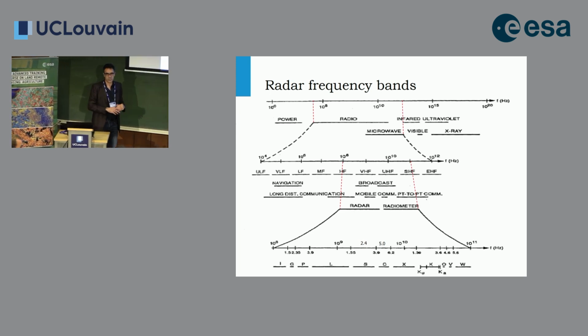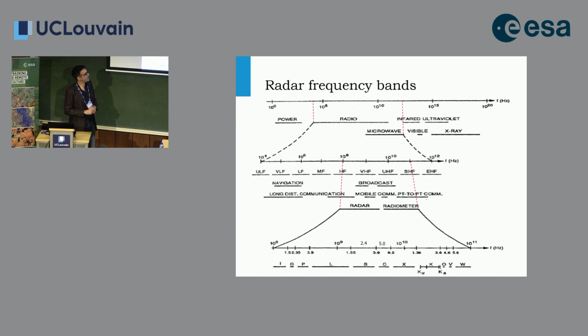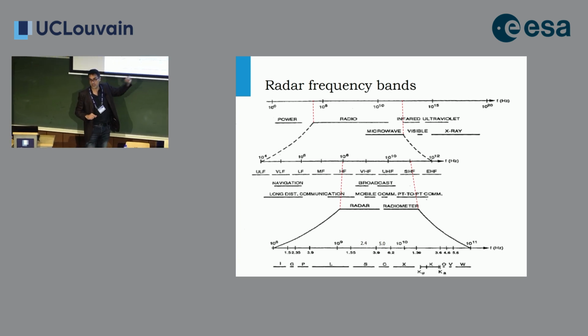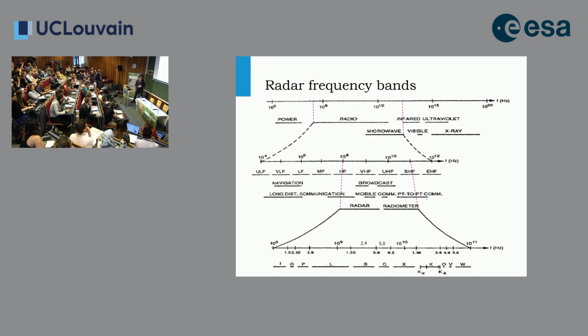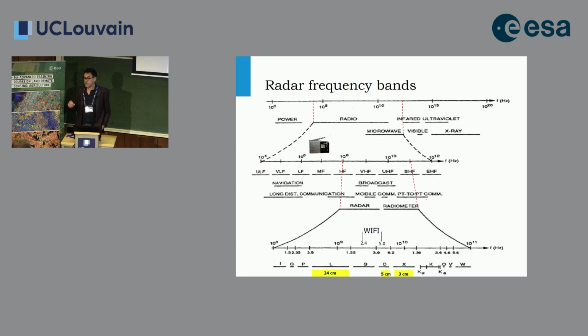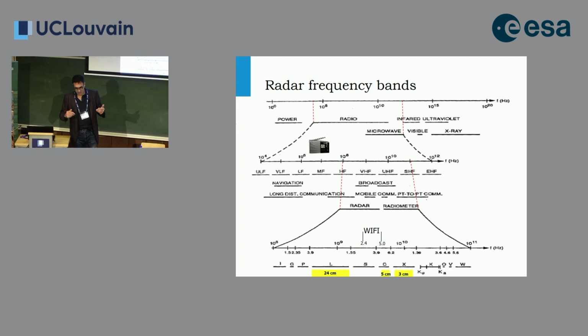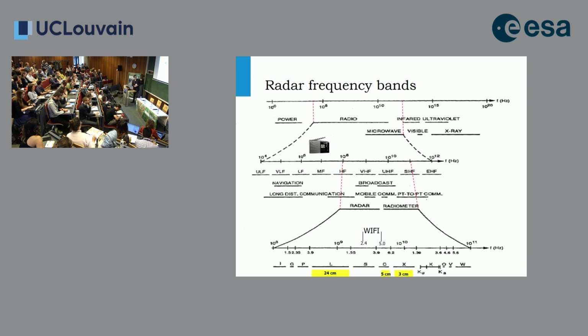In the past, when radar was developed, around the Second World War, maybe a little earlier, because of the military applications people started to give names to these different bands: the I band, the G band, the P band, the L band. These names do not make any sense, they were just codes. But one thing I always tell students who start with radar is that you need to know by heart three bands: the L band, the C band, and the X band. There's no way around it. X band is 3 centimeters, C band is 5 centimeters, and L band is about 24 centimeters. If you're talking to somebody in the radar domain, or you are the expert being asked for information, you simply need to know these. If you don't know these bands, you cannot have a good conversation about the topic. So please memorize this.